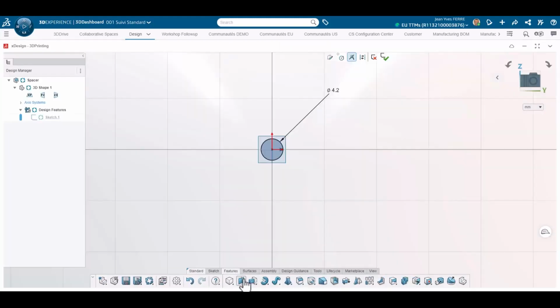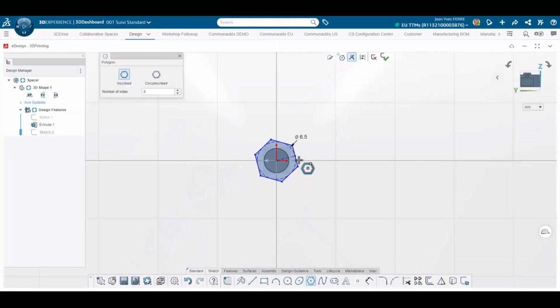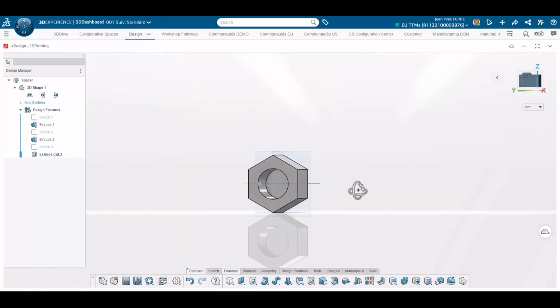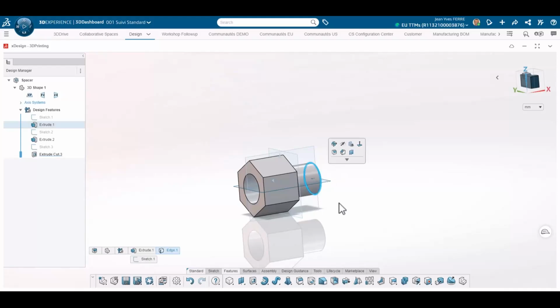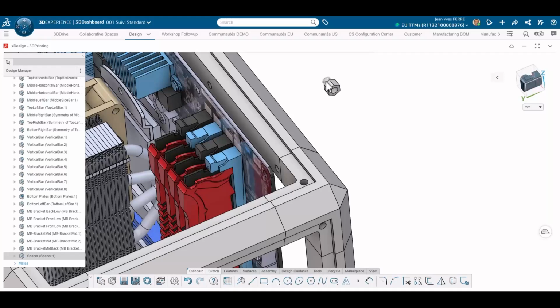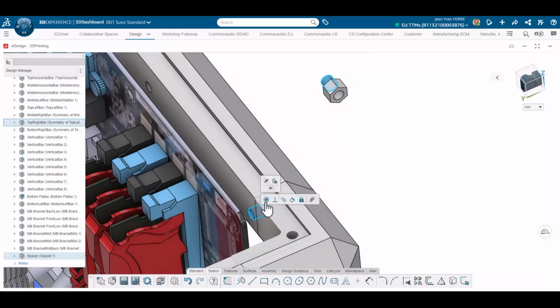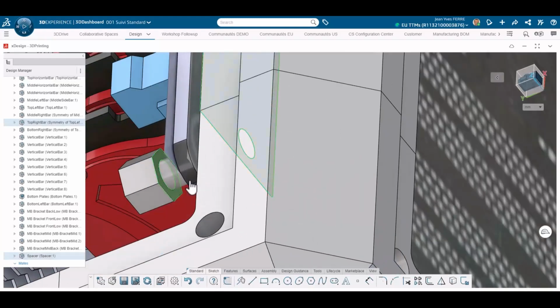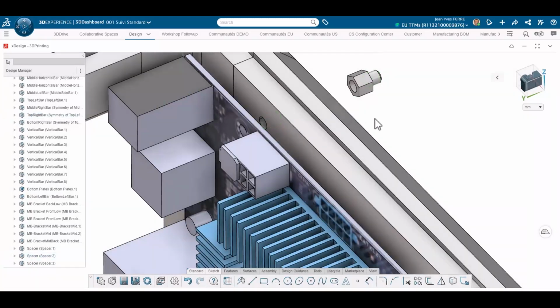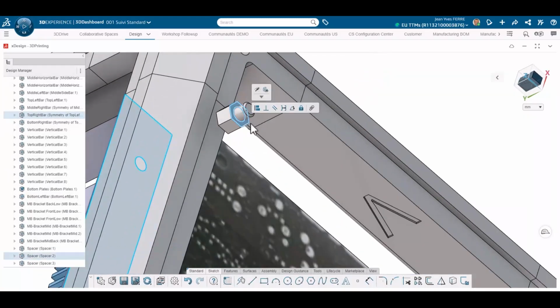I will reuse the same for the 3 mounting holes. I start with the screw and I add the hexagonal column. I took dimensions on the actual part and I chose the 5mm height, since this is the value I took for all other mounting parts. There is a hole to mount the motherboard and a chamfer to ease assembly. Now I add 3 of those columns to the assembly so the motherboard is correctly secured. I show mating for 2 parts only, but I don't doubt you can do it by yourself now.